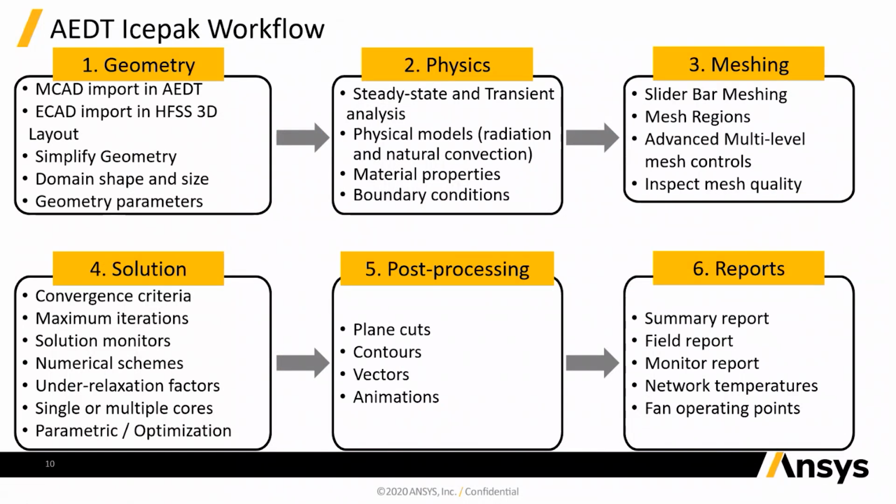Now let us talk about the workflow. For Icepak, the workflow is basically we bring in the geometry. We can bring in the mechanical CAD, which is the support structure, as well as the electronics CAD, which has the board, components, traces in the board. All of that can be brought in. We can solve steady state as well as time transient problems. And it captures all the physics, like we can have conduction, convection, and radiation. All the modes of heat transfer are captured comprehensively.